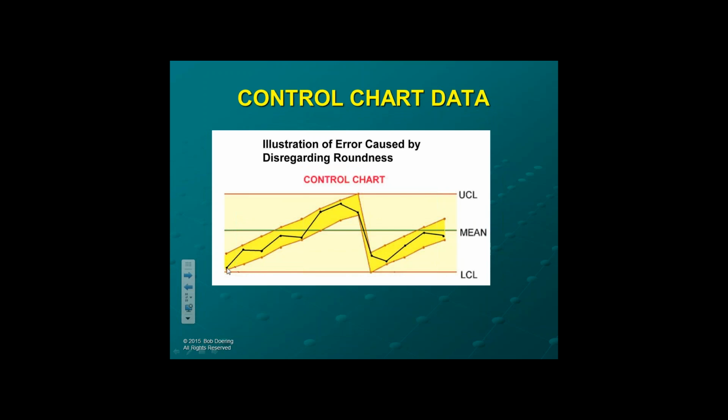If you had only measured one diameter, you would see this kind of variation occur on the black line. However, that variation is variation from measurement error. It has nothing to do with the process variation. It's because you did not capture all of the diameters.